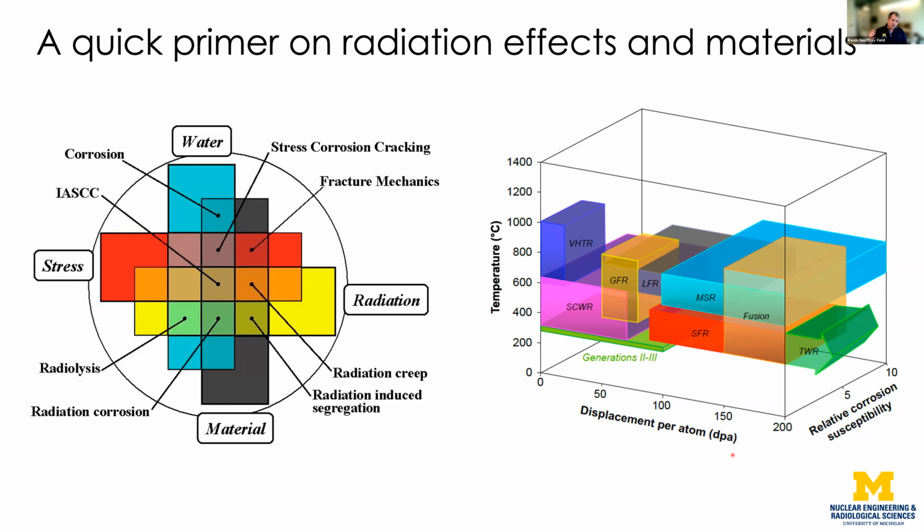The problem with that type of power generation is ultimately you involve neutrons, either in fission or fusion. You're going to have these high energy neutrons moving around, and they're going to create damage. You can think of it to a certain extent as somebody sitting there with a gun and shooting bullets at a wall. You're going to create these types of defects or problems with your material. And so as somebody operating a reactor, I want to know how that changes my material's performance, right? So what is my susceptibility to degradation due to radiation?